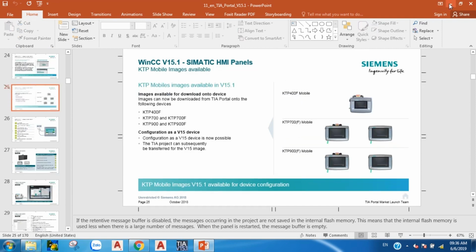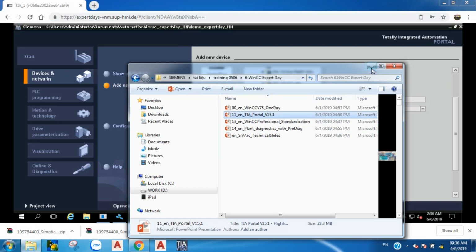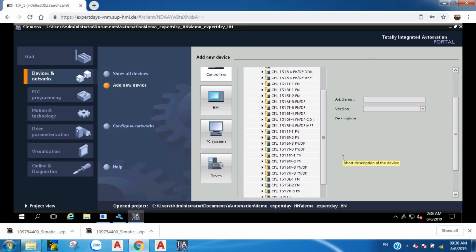So on a basic panel, well, the thing is, this function requires the TIA Portal installation on the system, because you need to have TIA Portal installed, not just the runtime running. So in the case of a basic panel, you don't have the TIA Portal installation on the system because it's a Windows CE system. So in that case, you use the graph viewer.